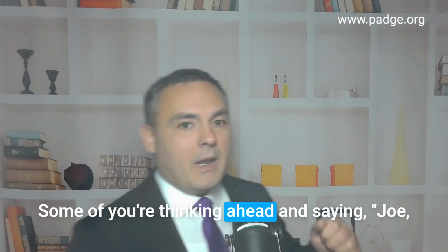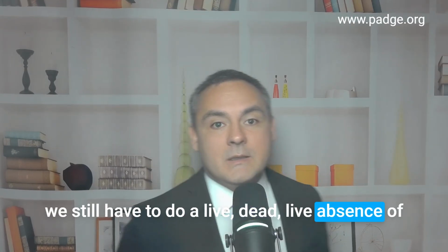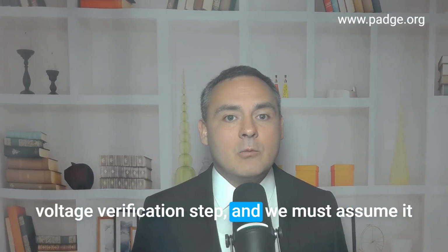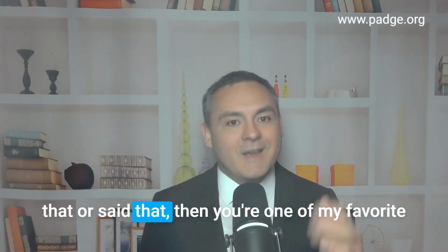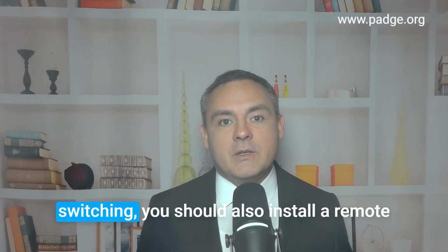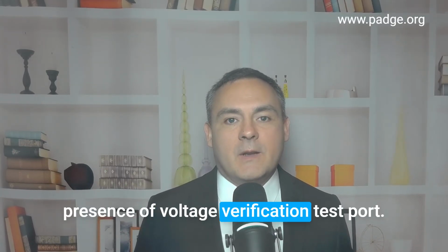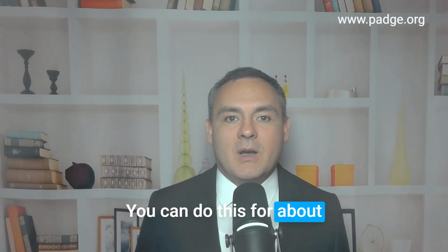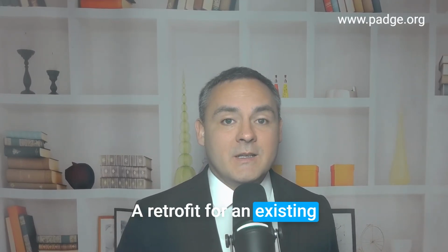Some of you are thinking ahead and saying, Joe, we still have to do a live absence of voltage verification step, and we must assume it is still energized until that's done. If you thought that or said that, then you're one of my favorite types of customers, a very smart customer. Therefore, to complement remote switching, you should also install a remote presence of voltage verification test port. You can do this for about $2,000 extra on your project. A retrofit for an existing installation is not that much more.